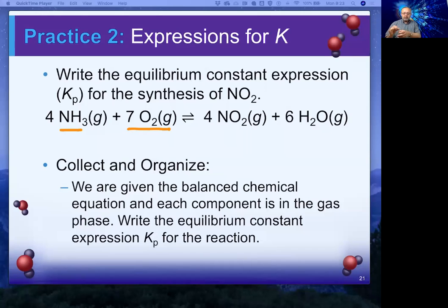And you open that, and it has a diameter of about, I would say, 8 to 10 feet. And it has a metallic mesh made out of platinum. That metallic mesh is the catalyst for this reaction. So this reaction is catalyzed through platinum to be able to transform ammonia into nitrogen oxides, which eventually lead to nitrates.